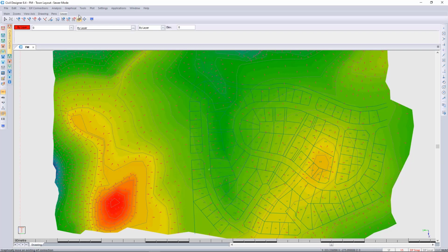And I'll go through to graphical add. Here you can see the max length of 80 meters has come through from the previous pop-up, but here is a new item which is offset. This is not to do with mid-blocks or road reserve. It is any offset from any CAD line. I'll make that also 2 meters and accept that.